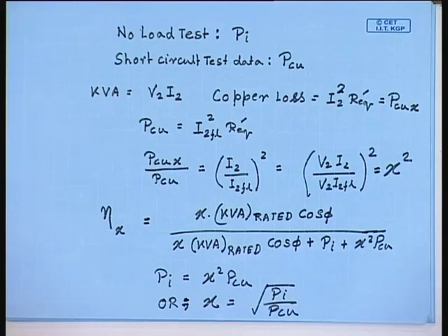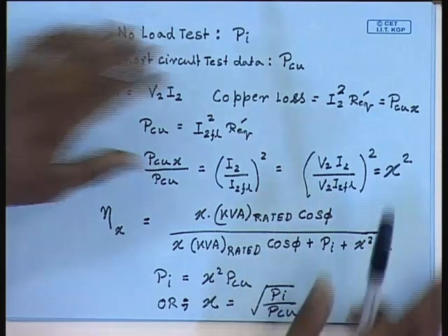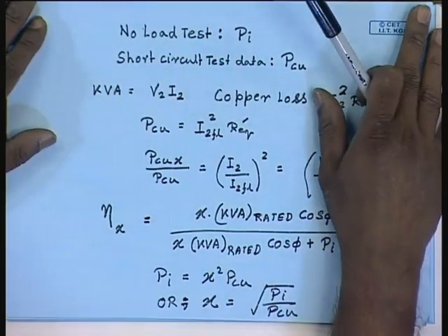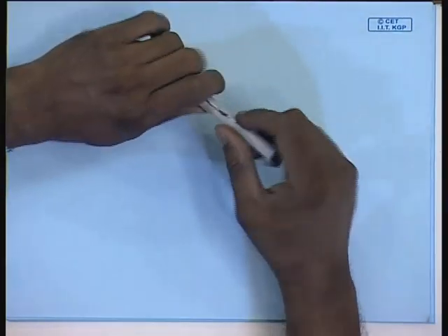Normally, it is expected that the loading pattern of a transformer will repeat every day in a season at least. Therefore, a more useful parameter in order to find out the performance of a transformer is called the all day efficiency.